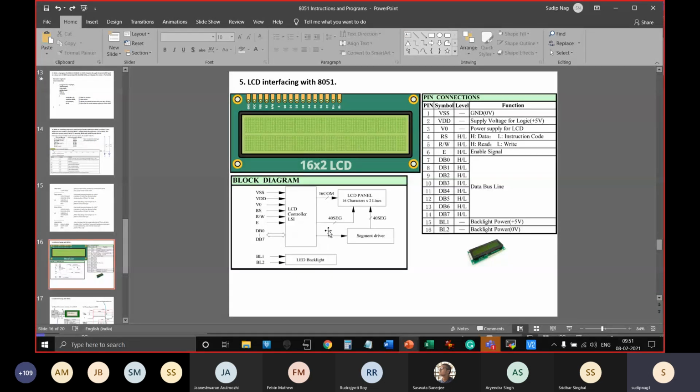So these are the backbone of any display device. Whenever we want to display something on the panel, we never have a direct connection to the panel, because the panel connections are quite large in number. There are hundreds of connections for every pixel. Some control signals are going between the controller and the panel through the driver. There are hundreds of control signals available, based on the number of pixels that you have.